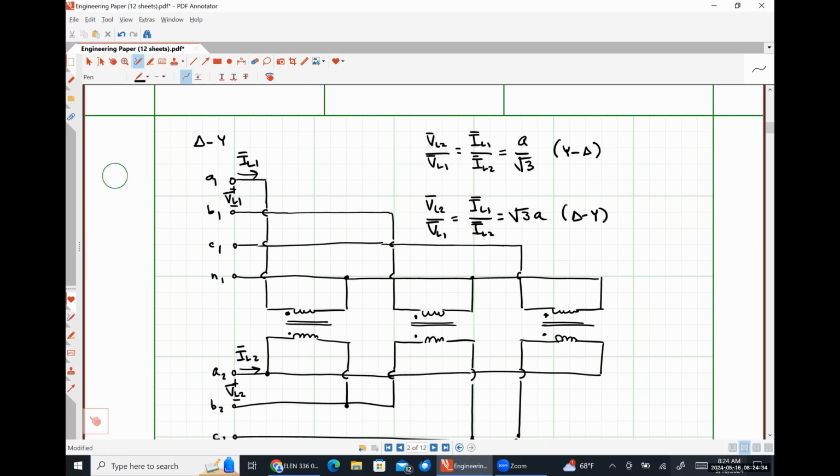But it's not as simple as just connecting up a generator and calling it a day. You have to match the frequency and all that kind of stuff, because if you effectively dirty up the power that the utility is providing, they are not going to be happy. So there are power electronics in there providing electrical isolation while also helping to maintain frequency matching, so that the power on the grid as a system is clean, and by that I mean as undistorted as it can be.